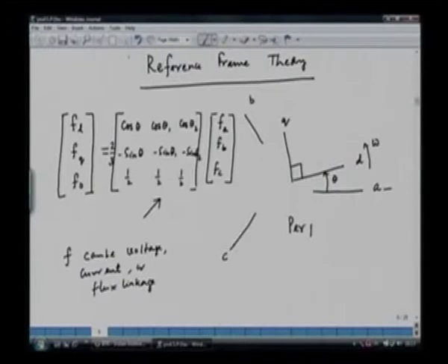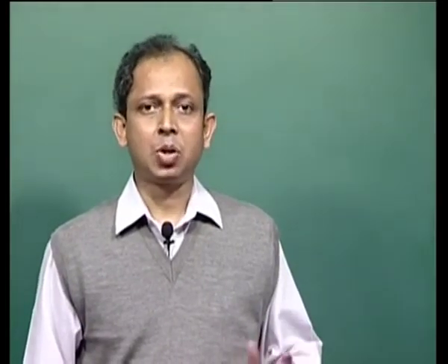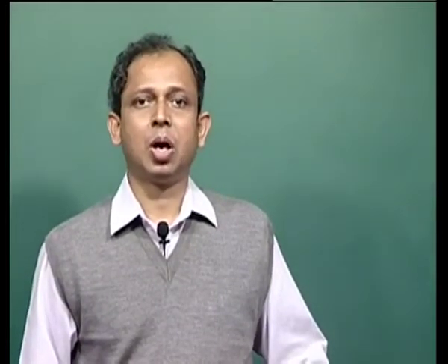So we have to take such a transformation which does not change the per phase power. So this is based on per phase power invariance, and that's why we multiply in this case by 2/3 so that per phase of the 2-phase system or DQ system is same as per phase of the 3-phase system, that is ABC system. The parameters are same, the variables are also same. So when converting from 3-phase to 2-phase, we don't have to change the variables or change the parameters.